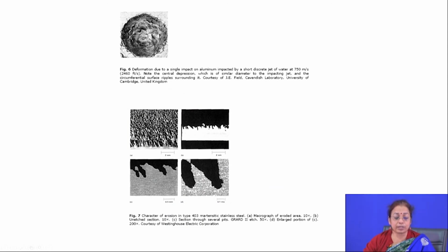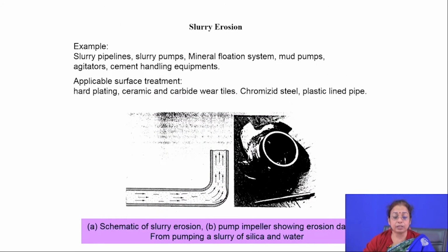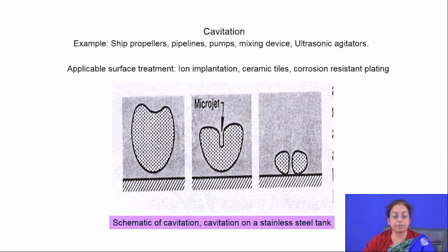So, after liquid impingement, you will see that the surface has a lot of pits. In addition, there is also some directionality on the pitted surface, because whenever flowing liquid interacts with the surface, the material removal depends on the direction of the flow. So, surface materials get removed along a certain direction depending on the direction of the flow. Now, the third type of erosion is cavitation erosion.